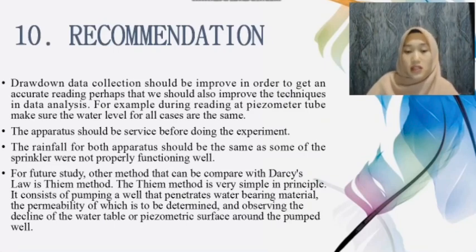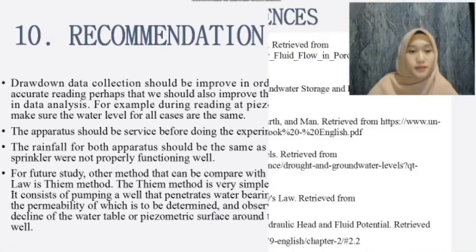The Theis method is very simple in principle. It consists of pumping a well that penetrates water-bearing material, the permeability of which is to be determined, and observing the decline of the water table or piezometric surface around the pumped well.